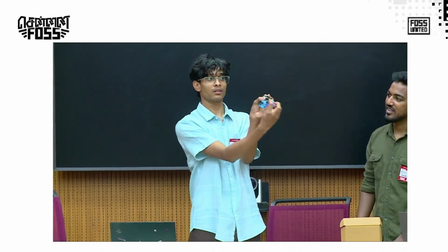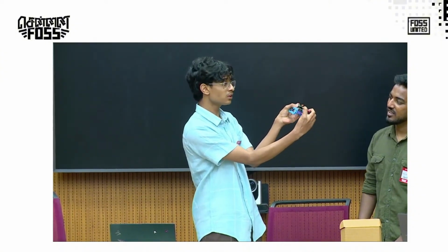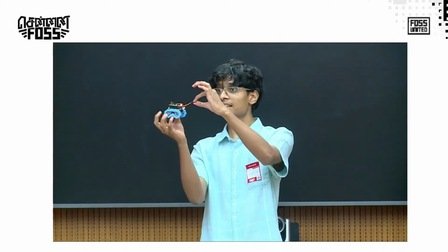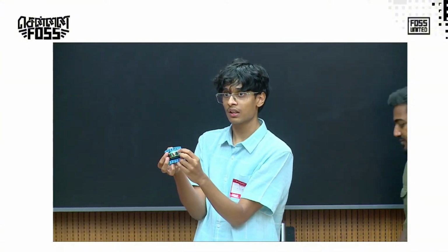Do the same for the longer servo wire, which should go on top of this. You pass it through the hole here, and you get the wire from the other side. It should be like this. Then you connect it to the top L shape. Again, make sure the yellow wire is facing towards the labeled pins here, S1, S2, S3.